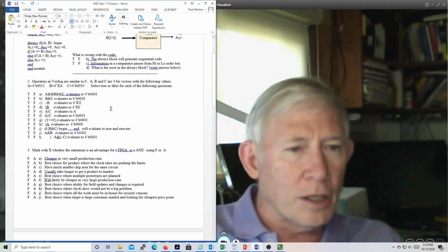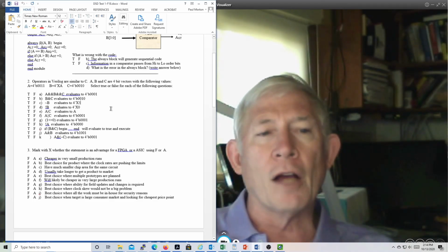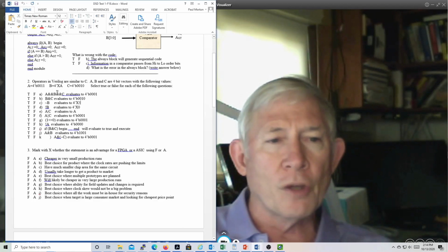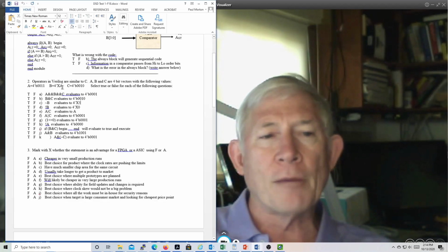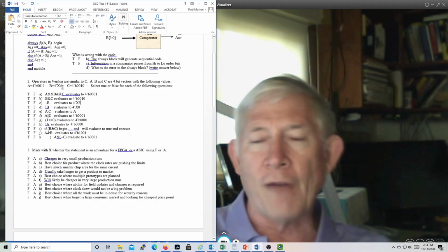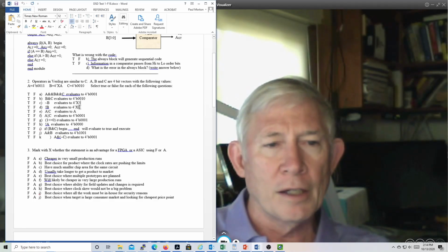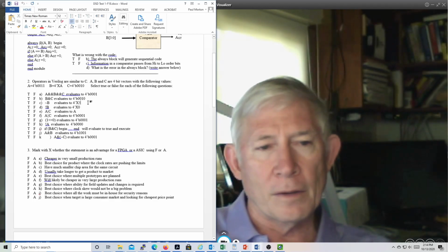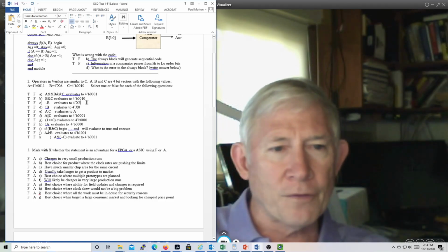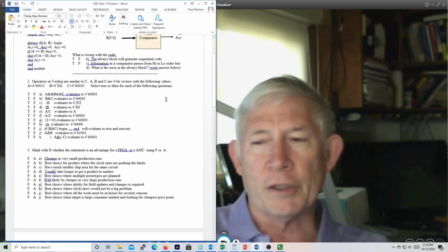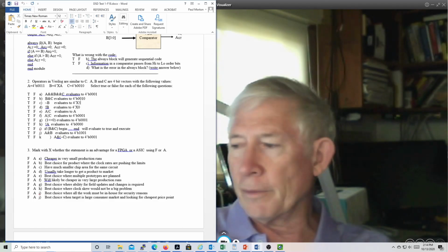Okay, next, tilde B is a bitwise inversion of B. So here's B. B is A. Anytime you invert an A, you get 5. And so it's going to evaluate to 4'hX5. All right, so that's a good question. What does the X mean?